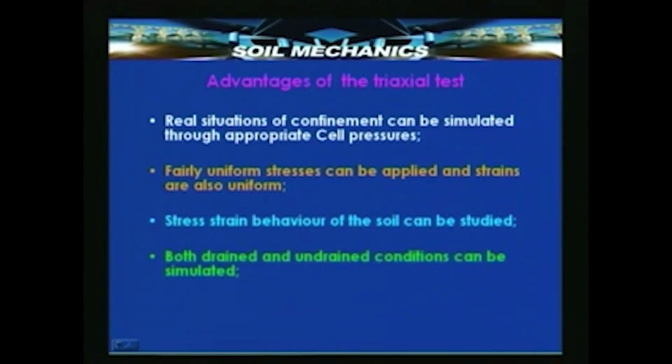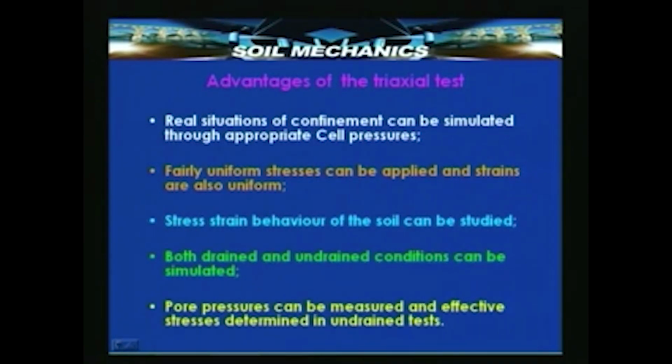Lastly, both drained and undrained conditions can be easily simulated in a triaxial test. In the direct shear test, on the other hand, we found that undrained conditions can hardly be simulated adequately. Then finally, pore pressures can be measured and effective stresses can be determined during the undrained test. This is a tremendous advantage, because the knowledge of the pore pressure tells us exactly what